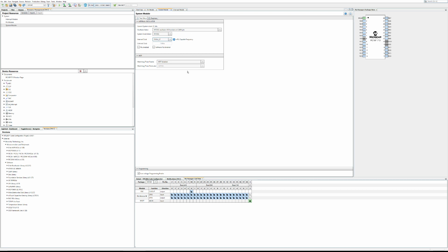In this state, the chip itself is very, very low power, a couple of dozen microamps. I'm not sure of the exact figure for this part, but very, very low. So it's nice to not use up many resources. In many cases, with the number of chips that this part can replace, it may be even more power efficient than discrete digital logic, which is a nice bonus. In this mode, you basically only need power and ground into the part for it to operate.